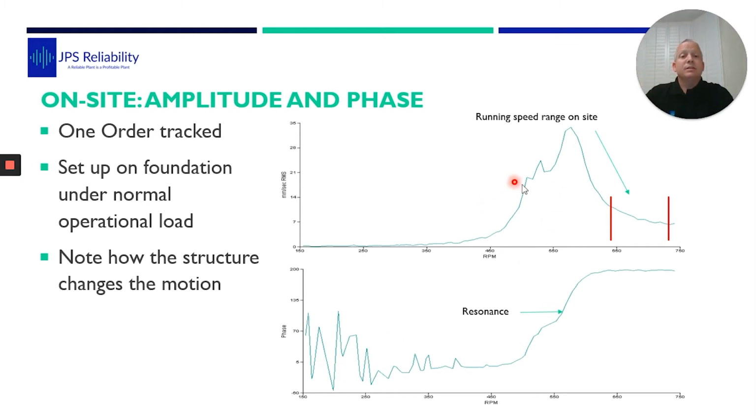But look at this here. Massive sweep through two resonances. And on the bump test, we had those two resonances close together. So this is matching exactly on the pump. When it's in there, it's doing that. It's moving on the floor. Here is our under speed, which shows the faster we go, the further we move out from the resonance.